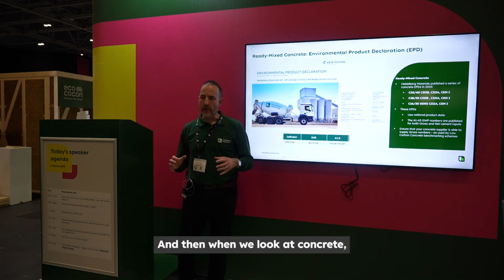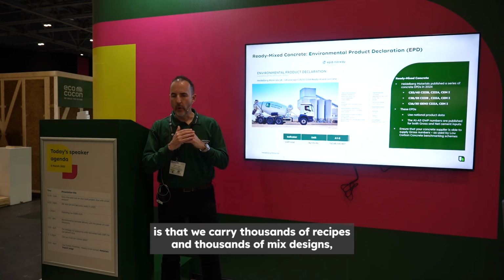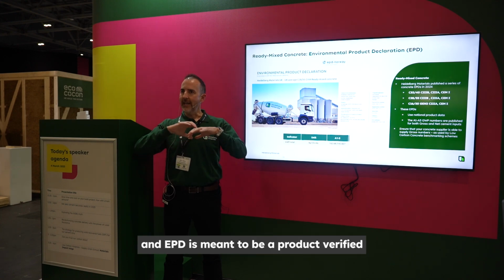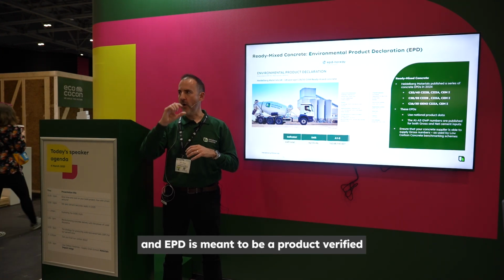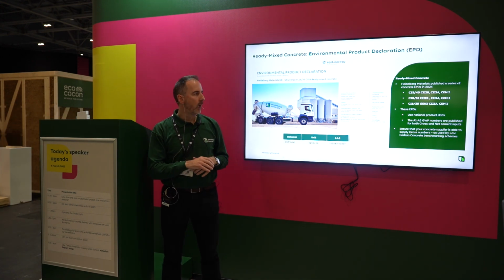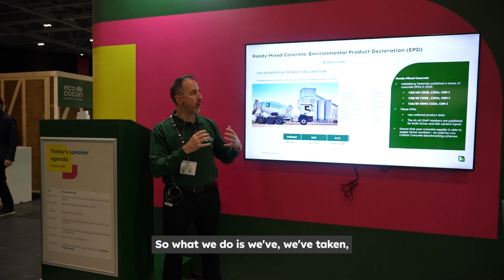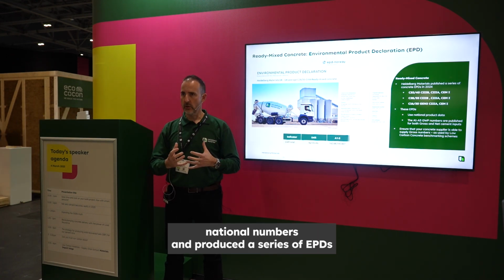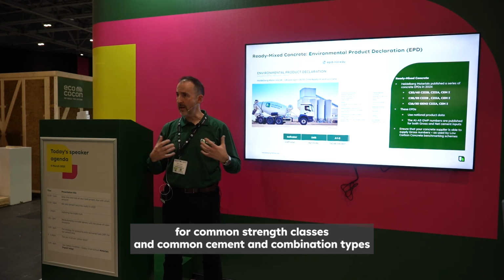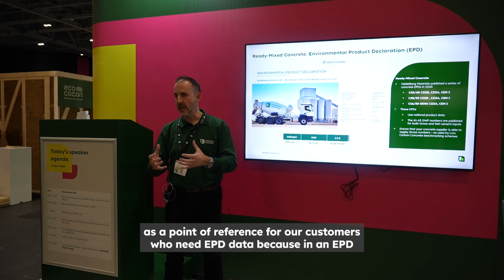And then when we look at concrete, one of the challenges you have in the world of ready-mix concrete is that we carry thousands of recipes and thousands of mix designs. An EPD is meant to be a product verified designation of the environmental characteristics, and that takes time and money. So what we do is we've taken national numbers and produced a series of EPDs for common strength classes and common cement and combination types as a point of reference for our customers who need EPD data, because in an EPD